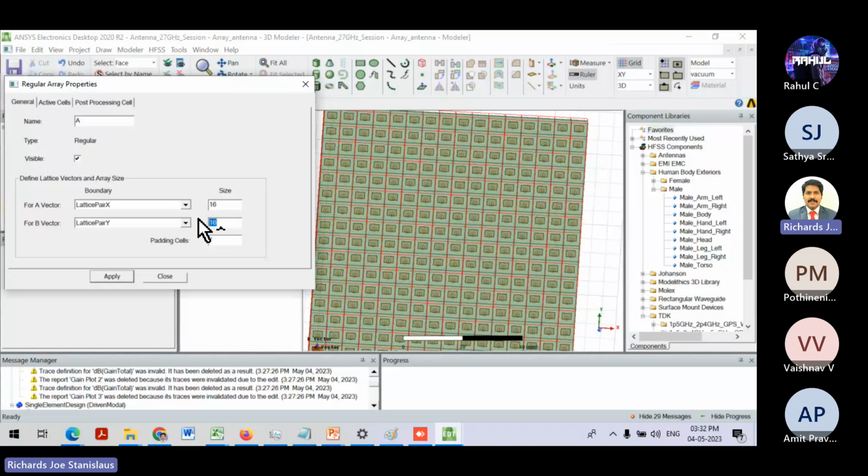Probably even 128 GB RAM or 256 GB RAM would be a bit less. You should really have a very high end machine. Instead, for a regular i5 processor, you can go up to a 4x2 array with 16 GB RAM. A 4x4 array can also be done. But if you're restricting the number of frequencies, then you can have the simulation done very quickly.